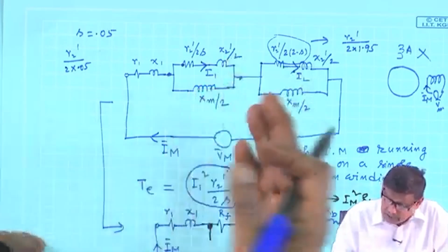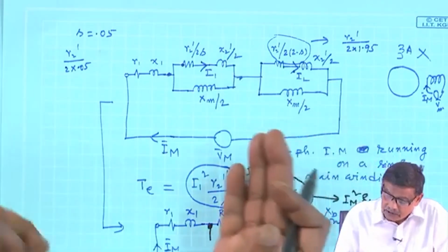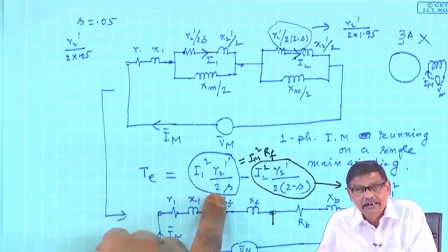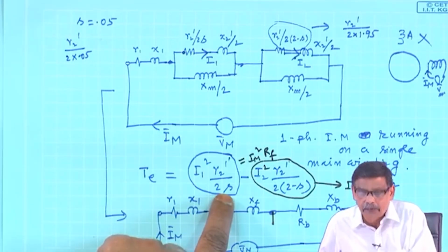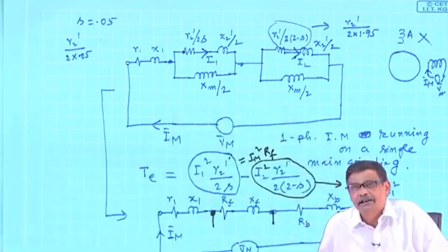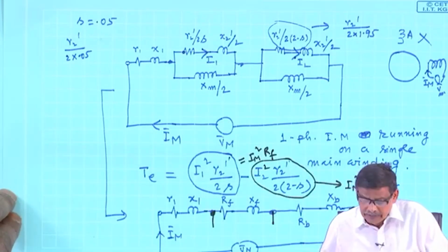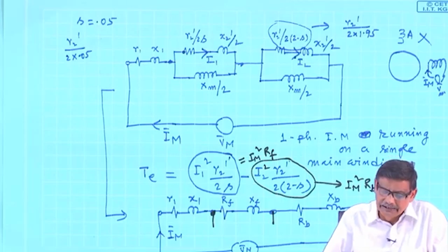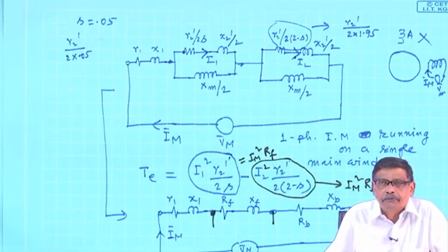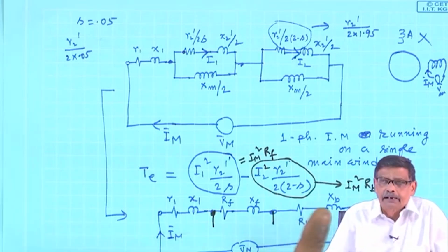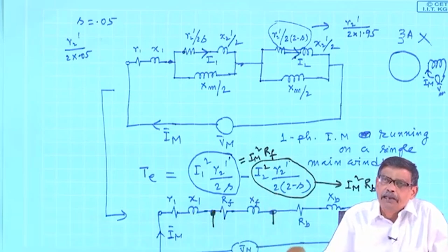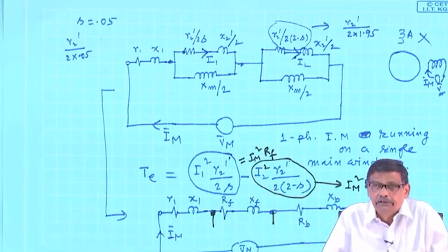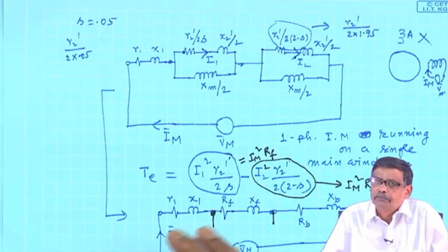Therefore, at that time I1, I2 may not be same, and not only that, that is the expression of the torque. If you put, better come straight here, S equal to other than 1, this difference will give you a resultant electromagnetic torque. Therefore, it looks like machine will develop some running torque. Is that clear? This is purely from mathematical point of view. So, it is correct, as the things were observed, the machine will be having running torque, but no starting torque is once again established here from the equivalent circuit.